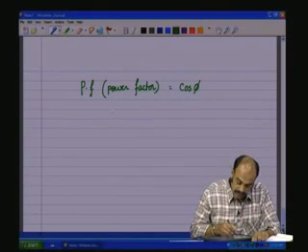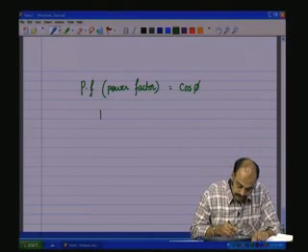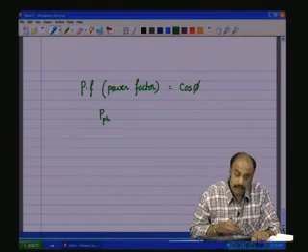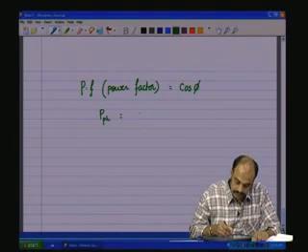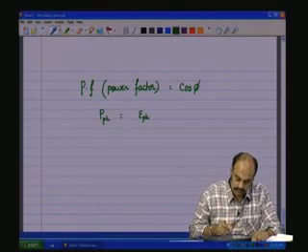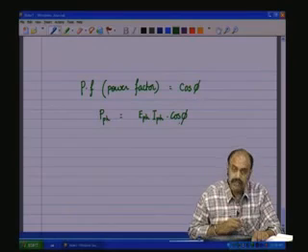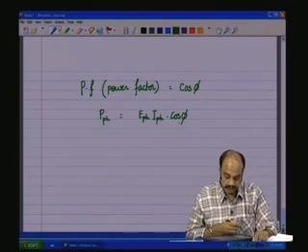So, the active power in each phase, that is per phase, will be E phase RMS value, of course, I phase RMS, the effective values, into cos of phi, as we had discussed earlier in a single phase circuit.